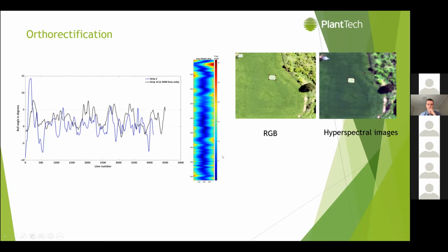As you see on the screen, the view angle from the sensor is highly jittery. This refers to the periodic instability and distortion of the sensor attitude, mainly caused by the variable speed and position of the aircraft, which leads to sensor noise and also affects the attitude angles: roll, pitch, and yaw.